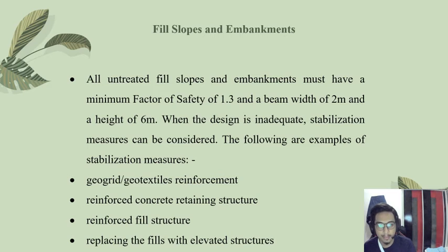Fill slopes and embankments. All untreated fill slopes and embankments must have a minimum factor of safety of 1.3 and a berm width of 2 meters and height of 6 meters. When the design is inadequate, stabilization measures can be considered. The following are examples of stabilization measures.